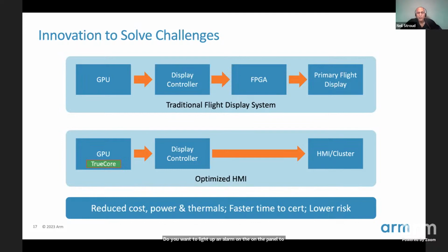So it worked very well, but obviously there's a significant overhead there, both from a hardware and software perspective, because you've got an extra piece of silicon on the board that's taking power and generating heat and making a bigger board. You've got additional software there as well that you've got to generate those test patterns with. So if you think about within avionics, every square millimeter of physical space matters, every milliwatt of power matters, every gram of weight matters.